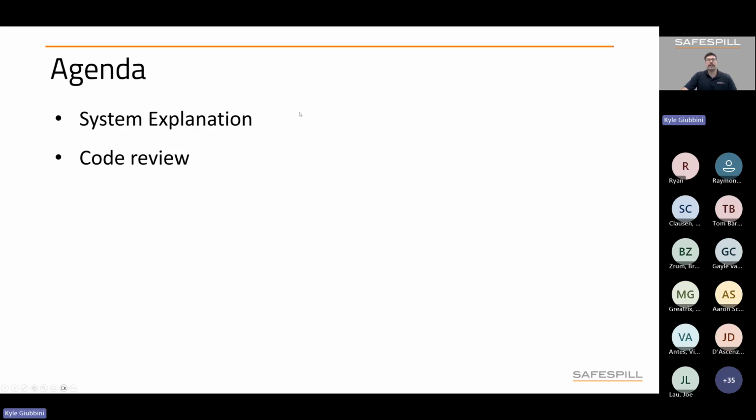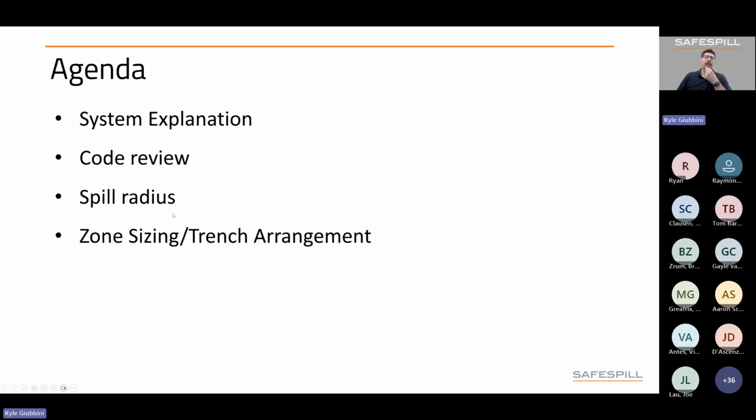From there, we'll look at the specific code provisions that discuss layout and sizing for ILDFA in NFPA, FM, and the UFC. We'll discuss Safespill's methodology for using spill radius to determine required footprints for ILDFA. We'll talk about some important parameters related to Safespill's manufacturing capabilities and constructability requirements involving zone sizing and trench arrangements